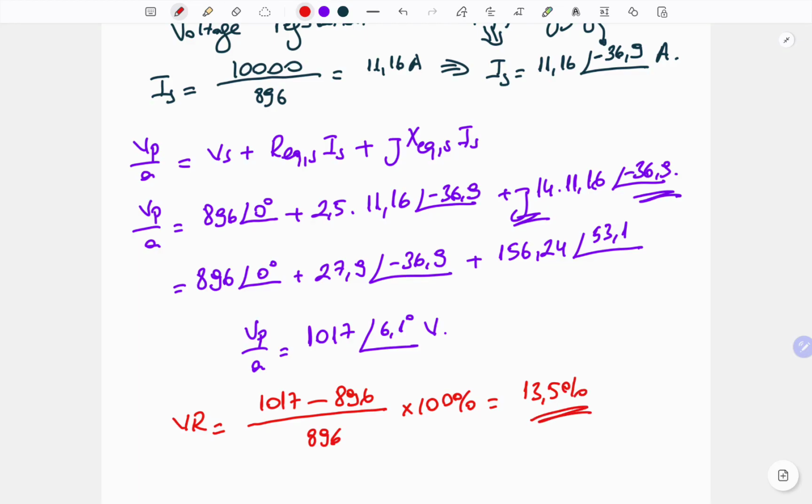Okay, so we have the secondary side no load and the loaded voltage values with the angles, and we calculated the current magnitude and the direction we determined. And in addition to that, we have calculated the voltage drops of the resistance and the reactance.